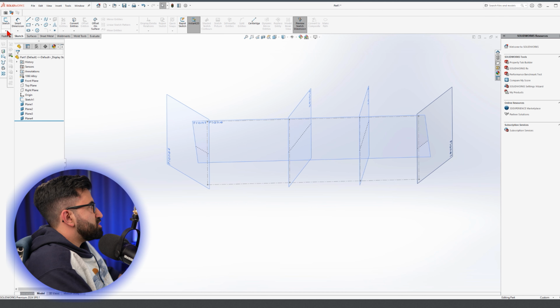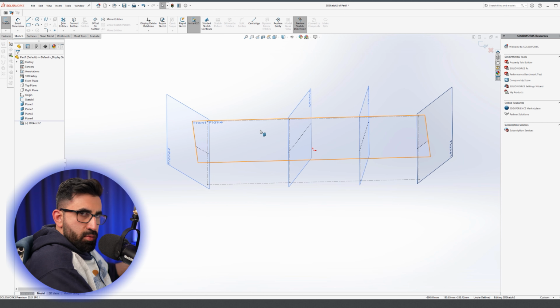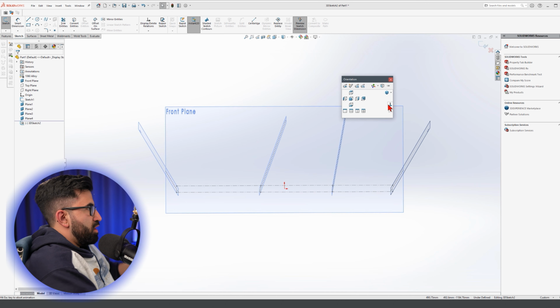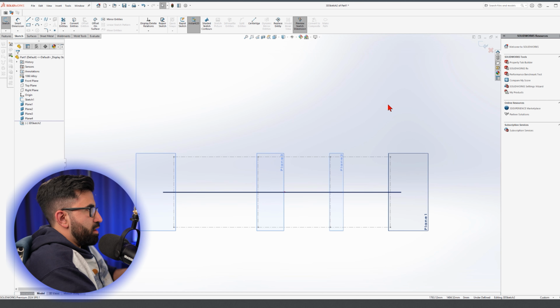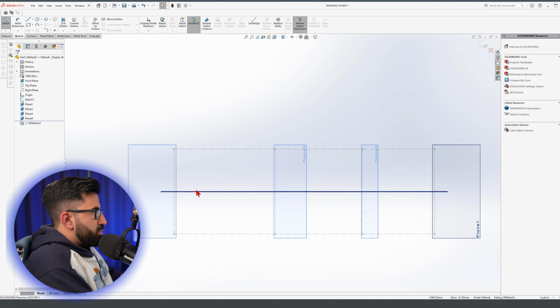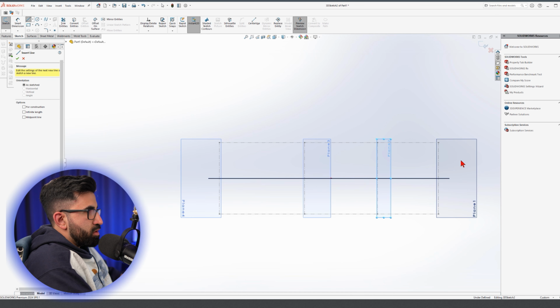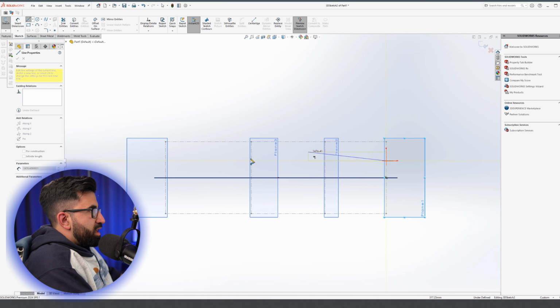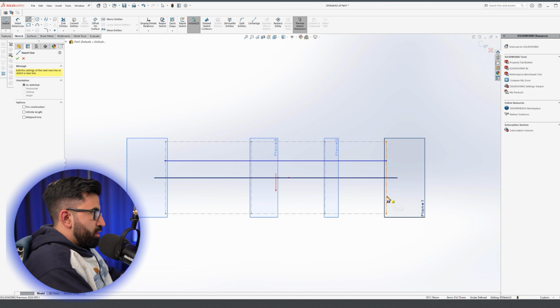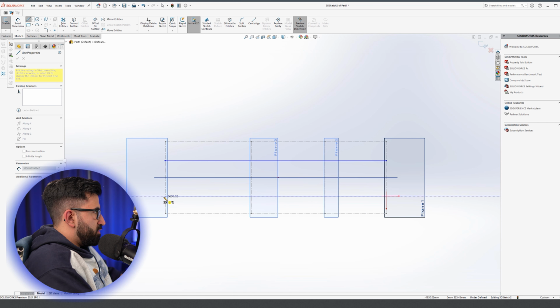So we go to the sketch tab, and for the first time we activate the 3D sketch. Right. So let's just look at our component from the top. We are looking at the top plane, and I'm going to draw the first line connected to this dashed line that I have, the back dashed line that we did as a 2D sketch and connected to the other end of the dashed line like this. Now, as you can see, my sketch is not fully defined.